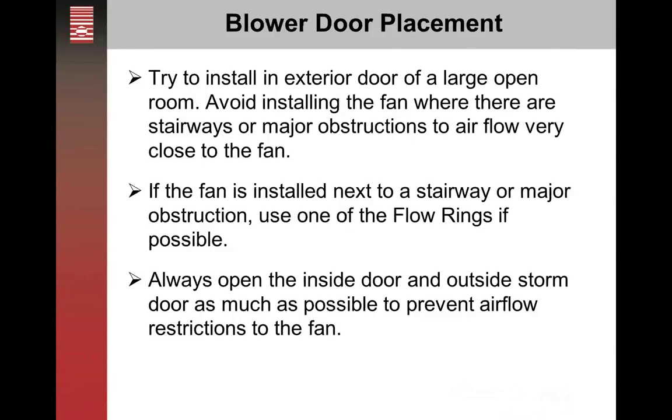When we're installing the blower door, we want to install it on an exterior door that has a large enough opening. We want to avoid installing the fan where there are stairways. For example, in Minnesota, there is a housing style called a split entry, where you walk into the house and have a very small foyer followed by a stairwell that goes up and a stairwell that goes down.